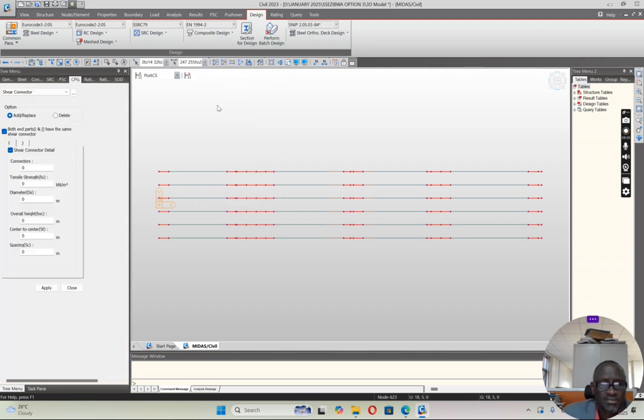Then we need shear connectors. Now this is where I told you about shear connectors. If you go to BS 5400 part 5 or even Eurocode, I think EN 1994 part 2 or something, you are able to see the spacing requirement, the minimum spacing, the H distance, the N distance, the diameter, all that, the connectors. How many do we need? I think here I'm going to say let's put 3. It depends. You may find 3 is going to be too much. It's going to give you ratios less than 1.5, so you can adjust to 2.